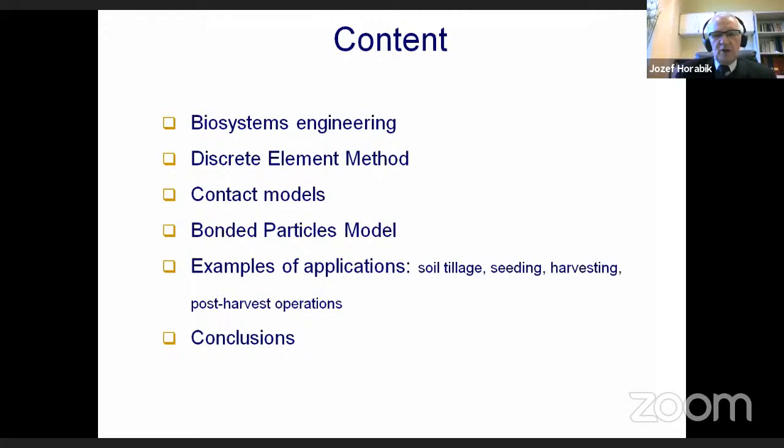In case of the small size particles, the adhesion forces should be considered in DEM simulation. Adhesion may originate from several sources, including van der Waals forces, electrostatic, or liquid bridge. Increase in the moisture content increases rapidly the adhesion.